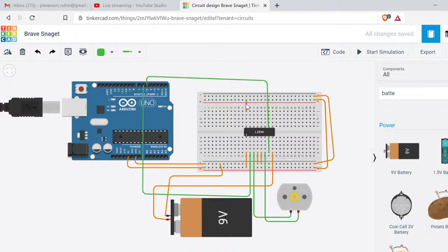Yeah, because this is an external power source, but we have to give power to the microcontroller, and this motor driver also. This is the maximum taken for running the motors. For programming the motor driver, we have to take the voltage from this Arduino or any 5 volts power.